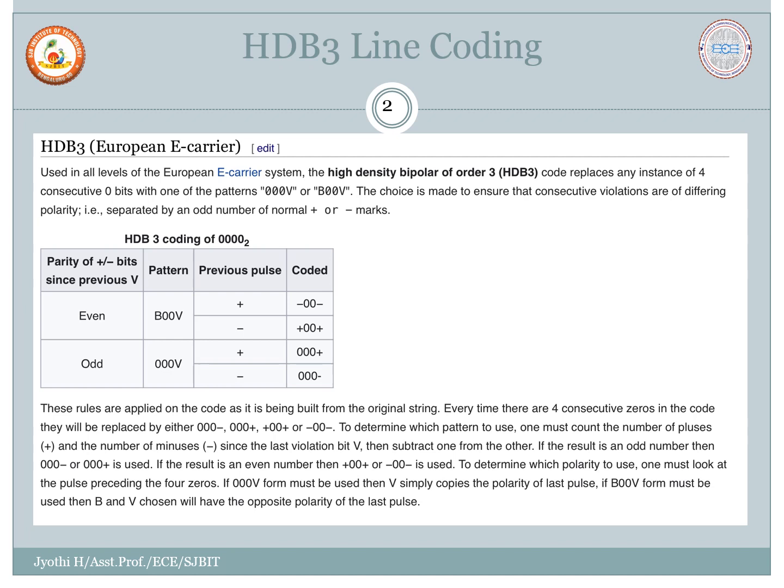So if at the receiver side it is going to receive more than 3 consecutive zeros, then this code is applicable. In place of the 4 zeros, it is going to substitute, so this is going to be replaced as 00V.